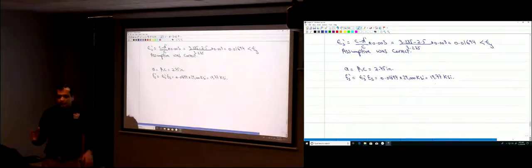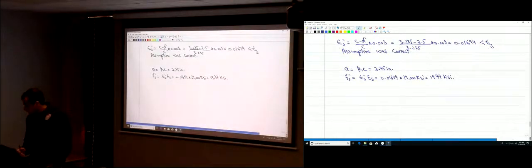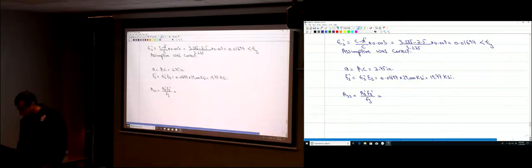You remember we divide our section into two parts. So there is an area steel. The area steel on the tensile side is divided into two parts. An area steel 2 that is resisting the compression force in the compression steel. So that's equal to area steel prime, Fs prime divided by F yield. So this is all from chapter 5, okay? I'm just doing the same analysis as chapter 5.